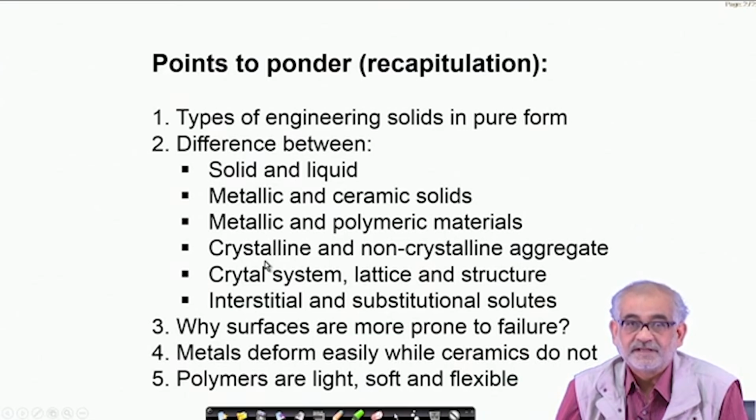We should now be able to understand the differences between the crystalline, which enjoy 3-dimensional periodicity, and non-crystalline aggregates which lack such 3-dimensional periodicity. We discussed the nuances of point lattices, then unit cell lattice parameters, crystal lattices or Bravais lattices, 14 of them, and then the infinite number of crystal structures that eventually can arise out of these. But we must not forget that no matter how complex a crystal structure is, if it is crystalline, then it must be related to one of those 14 Bravais lattices.